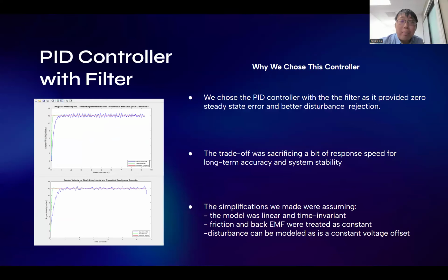So we chose the PID controller with the filter as it allowed us to get zero steady state error and better disturbance rejection. The trade-off was sacrificing a bit of the response speed for more long-term accuracy and system stability.